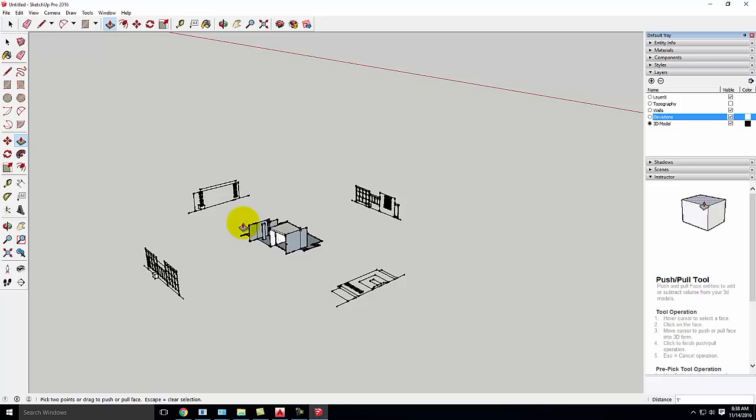The more detail you have, the better off you're going to be when we start doing elevations, plans, sections, and the perspective drawing at the end. Right? So lots of detail is important. You do not, in this, have to assign materials. Some of you that have worked in SketchUp before have played around with materials. Sometimes it's useful to assign glass, just so that it's a little bit transparent. Beyond glass, it's really not worthwhile, because we're going to end up doing materials and stuff in Photoshop afterward. Okay, so just keep it as plain gray, but if you want to put glass in, there's nothing wrong with that, so you can see the transparency.